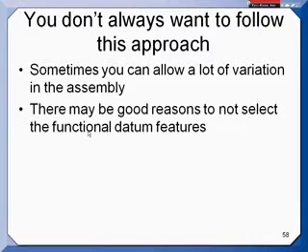I know one I've run into a couple of times is where you have a highly polished bearing surface, and you really don't want people touching it to inspect. And so you'll use something else to come in contact, but you control the tolerance between those two features quite tightly.